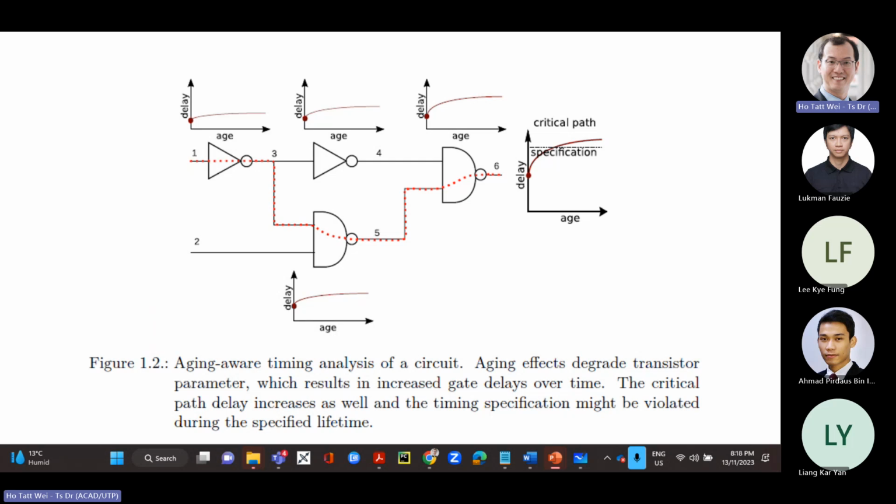Although it's the same design, each chip would have slightly different delay or specification that's achieved because of variations in the fabrication process. What type of variation? Line edge roughness, variation in the oxide thickness, variation in the random dopant fluctuations, RDF or RDD. And then all these cause variations in the threshold voltage and also variations in the current, which leads to variations in the delay. So same design, sort of different chips emerge.